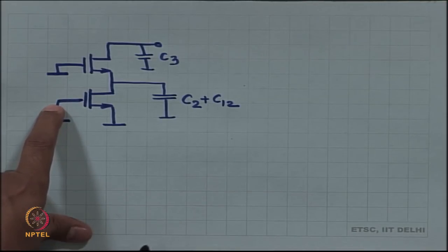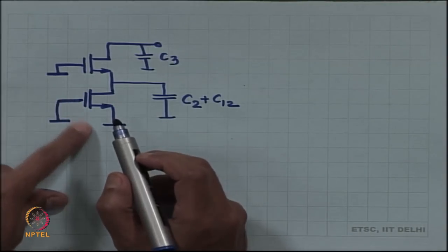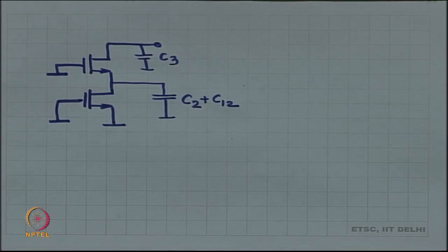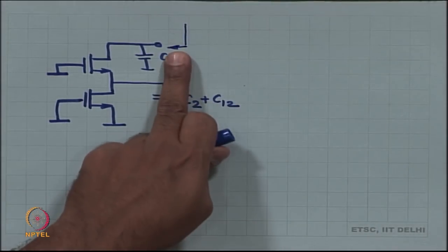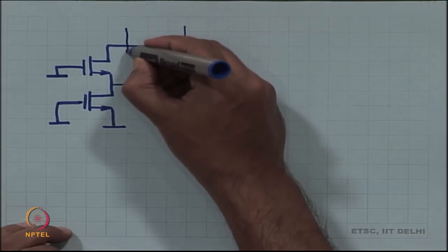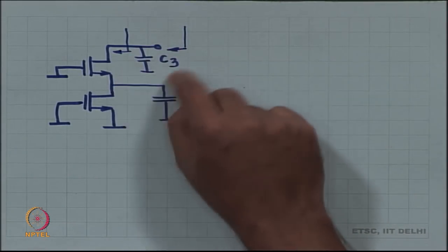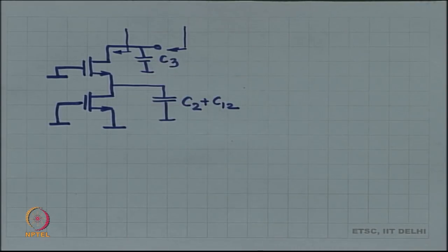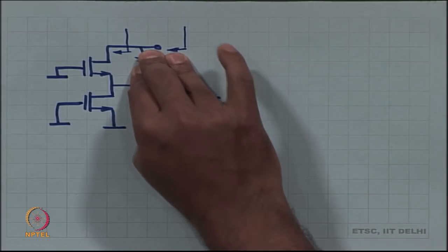C1 does not matter anyway, because it is now grounded on both sides. Okay. There was a C1 over here, that is now shorted, grounded on both sides. So, it can't take any current. All right. Now, we have to find the output impedance of this. Output impedance of this is 1 by SC3 in parallel with output impedance looking into the drain. Okay. So, 1 by SC3 is just the extra stuff. Let us do that later. Let us place that parallel piece later on.